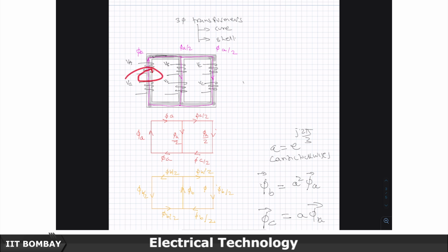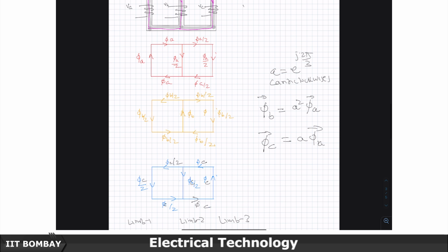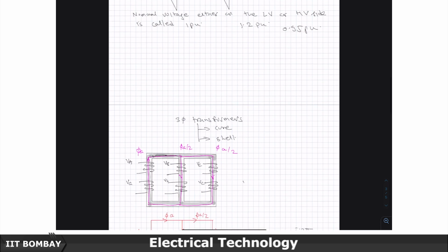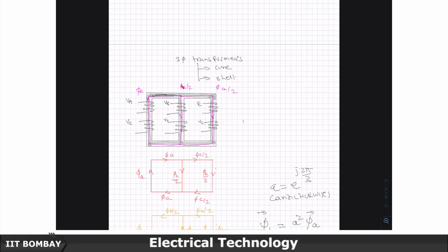So, you do not want the core to go into saturation. If the net fluxes are somewhat higher, then the area of cross section has to be taken care of in that particular way. But other than that, the device will not have leakages. The point which I am trying to say is, if these fluxes would not sum to 0, then where do they go? Then they have to flow out through the air outside, through the tank outside and then close the paths and come back, right, because in our magnetic circuits, we are just treating them using Kirchhoff's current law only.